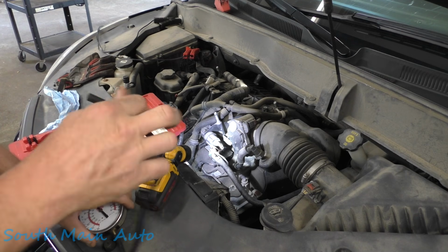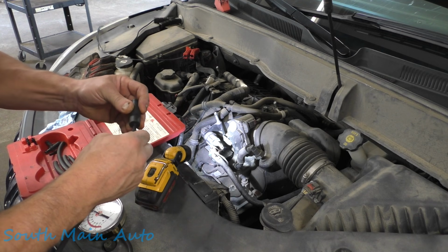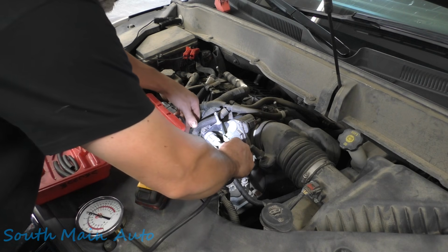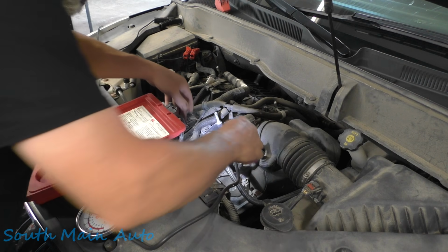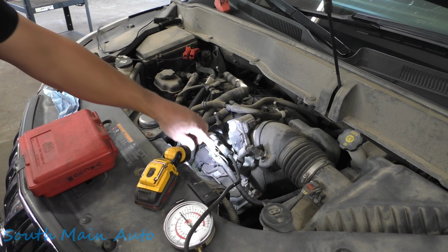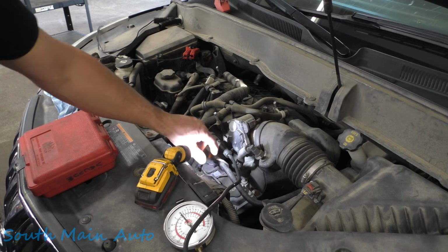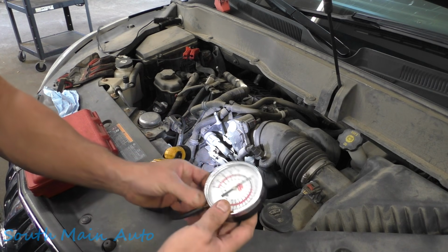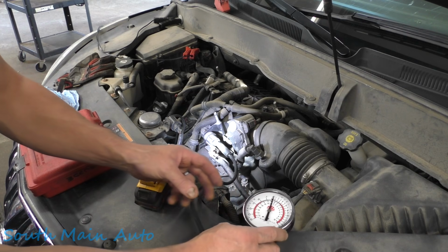Like I say, sometimes a little screwdriver whack will make them work again. Stick that on there. I'm going to go ahead and start up. The fans are going to be roaring again, but if this is still broken, it's completely unplugged, so that, you know, the PCM can't be commanding it. And then we should see it build vacuum.